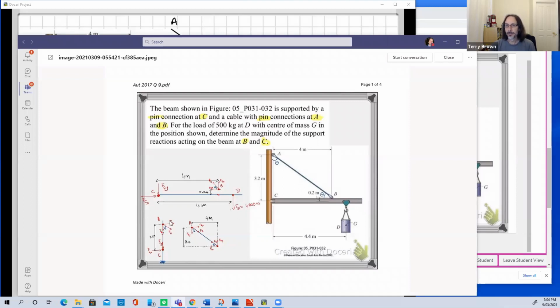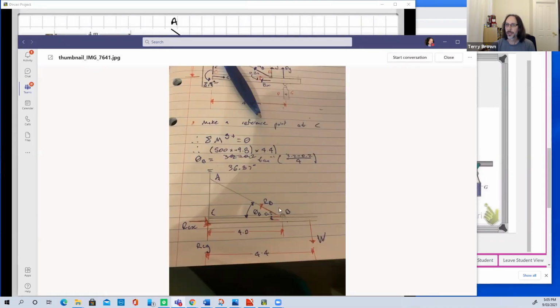All right, and same down here. Right? So here we're showing the forces that the post exerts on the beam, whereas when we draw the free body diagram of the post, we should be showing the forces that the beam exerts on the post. Okay, so that's our original one. This is good. This is what we were looking at before, but we're now looking at the free body diagrams of the cable and the post.